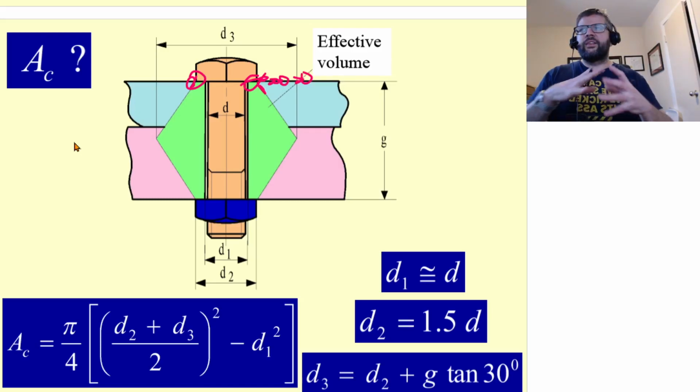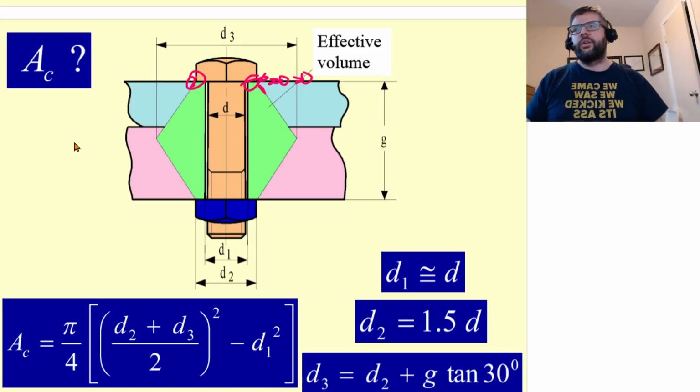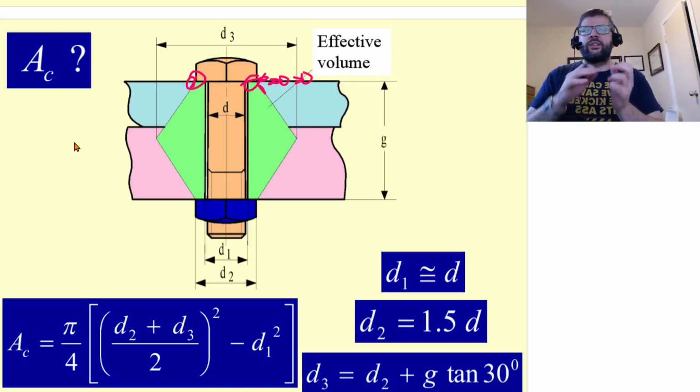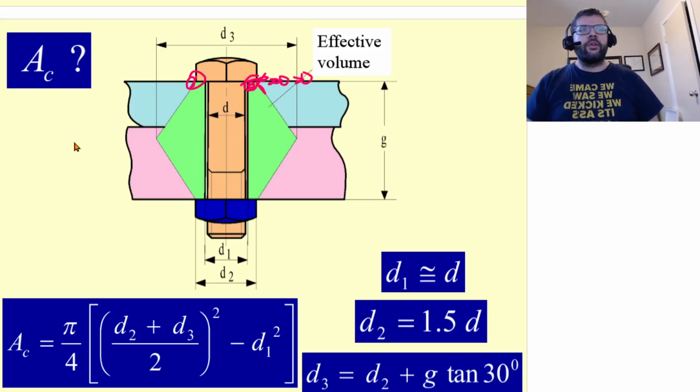So you can't say that it's spread over the entire cross section of the materials being bolted together, because it's only the little bit in between the bolts that is getting squeezed together. But it does spread a little bit. So you get the compression at the middle, and it spreads out, filling a certain volume. It spreads out until it hits a maximum point, then it stops spreading once it hits the middle, and then goes back down.